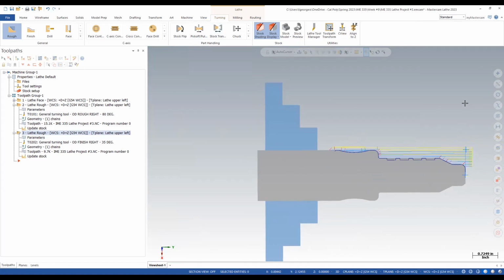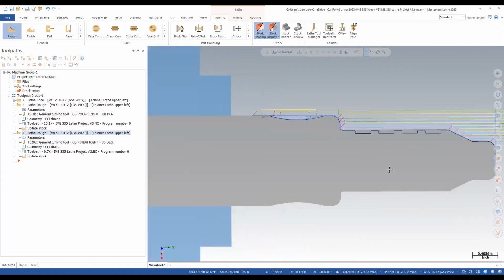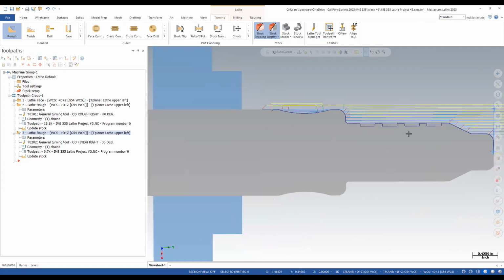I have to finish. Now, to be honest with you, it's easier to do one toolpath and make geometry for that one toolpath. What if I pick plunging and I pick all this geometry, what's it going to try to do? It's going to try to plunge these grooves, but then it's going to come up here and plunge this to finish that, which it needs.